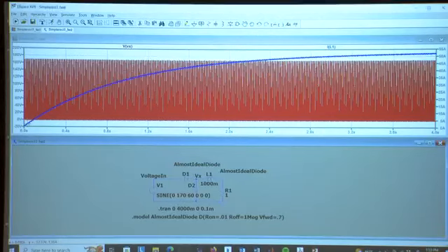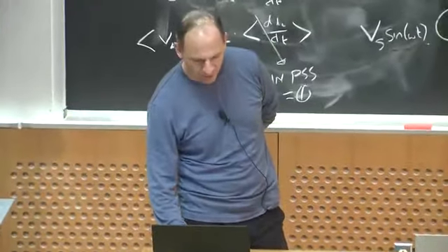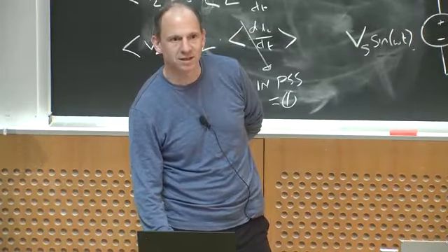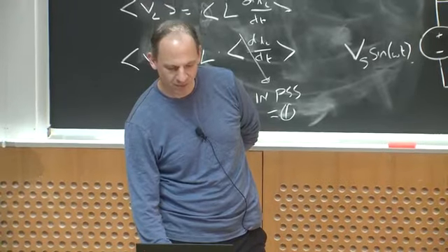But look at the inductor current. What do you think's happening here? This is the inductor current building up over time. The blue waveform is I sub L starting at some time equals 0. It's not constant. If I look at this, would you say that this blue waveform, you can see all of these cycles going on, is in periodic steady state? No, it's ramping up over time.